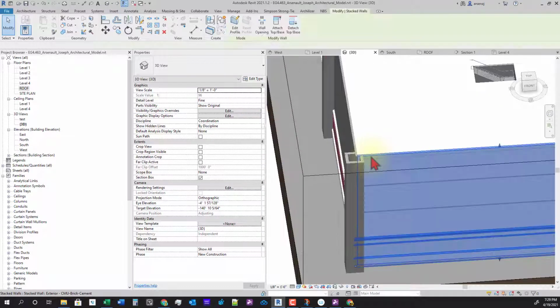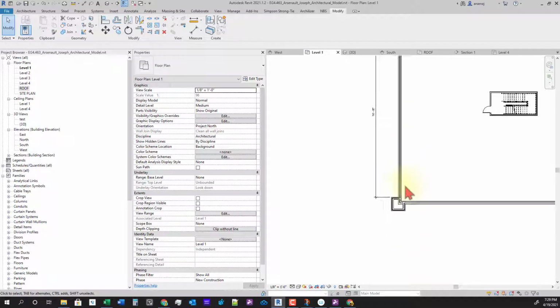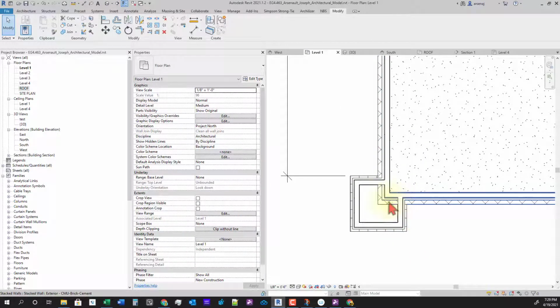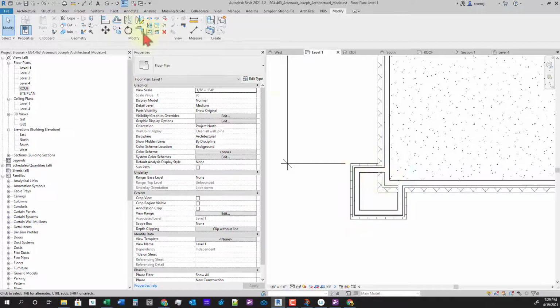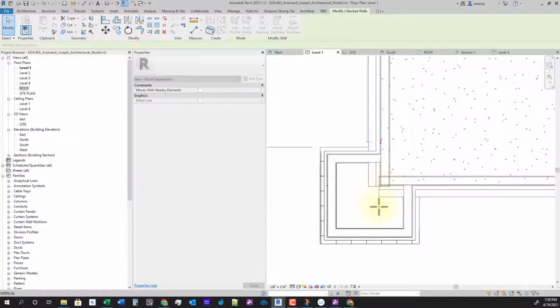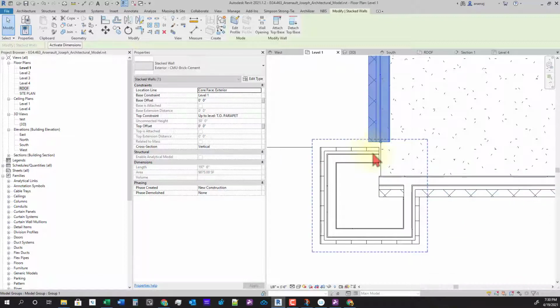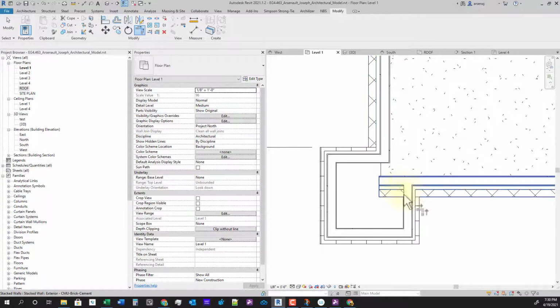I think the next thing I want to do is, because they don't really need this, obviously they don't need this wall in here, this cement. So let's try to trim this wall, see what happens. So nothing's happened. I'm going to try to just drag it. And what's it say? Expand, can't keep elements joined, error. And we'll just hit unjoin elements. And we'll hit trim and trim these corners up.